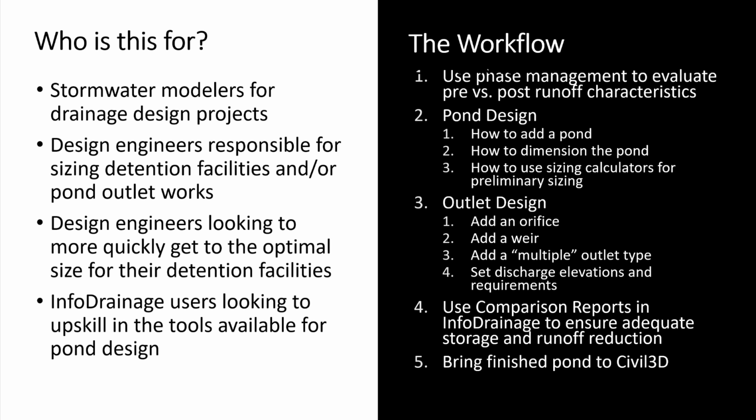We'll add a few different outlet connections as well as a multiple outlet type. So something to model essentially a structure that has multiple orifices, or a weir and an orifice, or a weir and a gate. And then we'll also show how to set discharge elevations and requirements so that we are controlling the rate of discharge from our site.